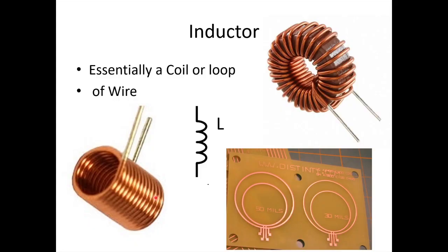So what's an inductor? An inductor is essentially a loop of wire. Now, you'll notice these are all shorted together because the purpose of this is so I could change what contacts I use for which circle using an X-Acto blade. So don't mind that they're all shorted here, but essentially a loop of wire. And then a coil of wire is another kind of inductor, where by having multiple loops ganged together in a coil, you can increase the inductance dramatically. You can also increase the inductance again by putting not an air core, which this is, but a ferrite core in the coil of wire.